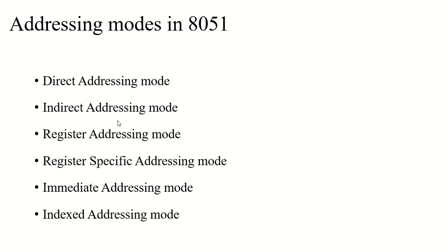For example, let's take another one, MOV @R0, 85h. What would it do? It would copy the data at address 85h to the memory location whose address is specified by the R0 register of whatever bank is selected. So here you are using @ to indicate the register as a pointer.